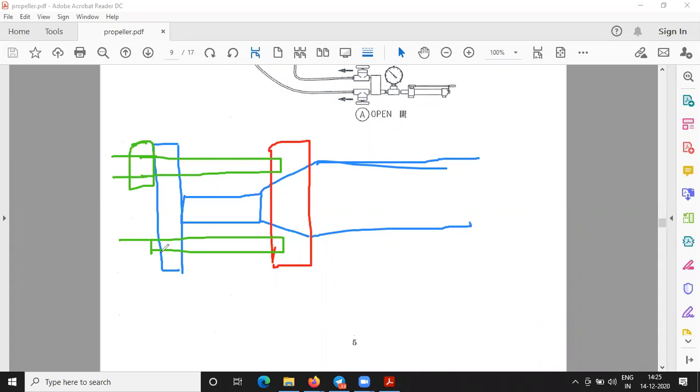As we jack up with this nut, what happens? It starts pulling the boss out of the tail shaft. But in this case, there were wear and tear. Similarly, we don't want this wear and tear. That's why the simple thing we do is reduce the friction between the tail shaft and the propeller boss, because friction is the only thing holding the propeller boss in place. So when you give some distance and reduce the friction, the propeller boss has to slide down on its own and hit the cushions. Understood?